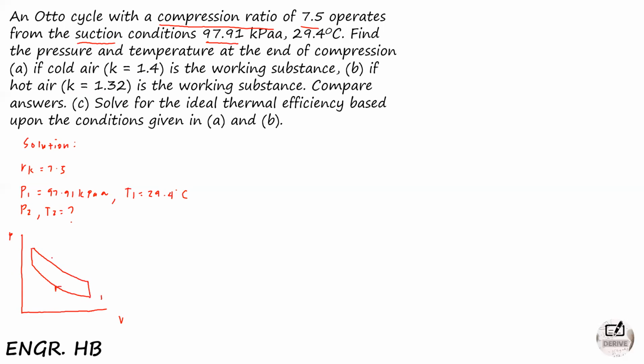So, this is your point 1. This is isentropic compression. Of course, this is isovolumic. So, 3 to 4, that was S is equal to C. And of course, this is isovolumic again. Okay.